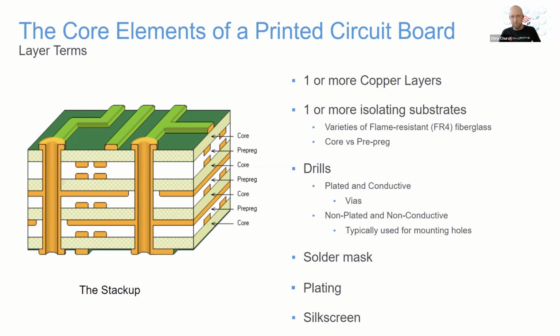You'll see those referred to as FR4. And one of the other things you'll see with that a lot is that each of those fiberglass substrates you're working with will have a different temperature handling ability. And where that really becomes important is where your device is being used. Like we see people developing products for, say, use in mining, etc., where the temperatures can get very high underground.